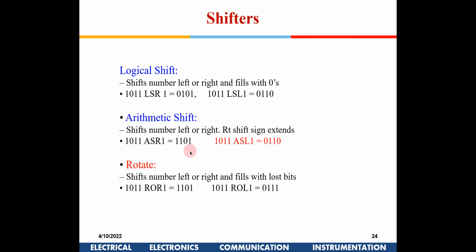For example, you have data in a register. If you shift it towards the right, it is like division. If you shift it towards the left, it is multiplication by 2, right? So every shift left is multiplication by 2. With the same data, you push in 0 and keep moving it towards the left, it is like multiplication by 2.